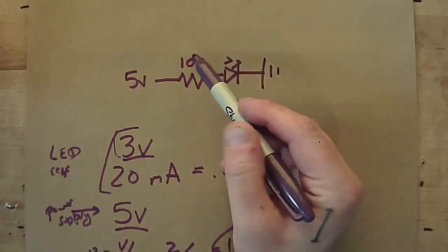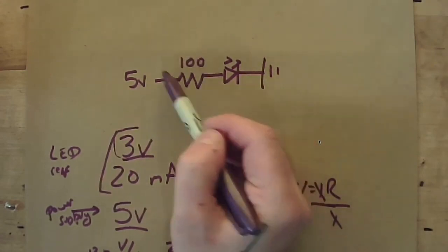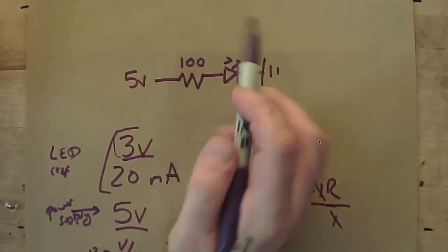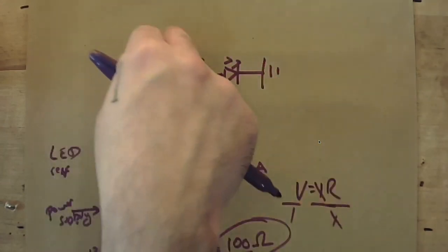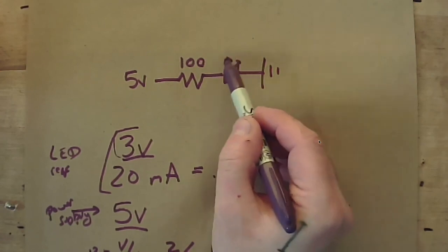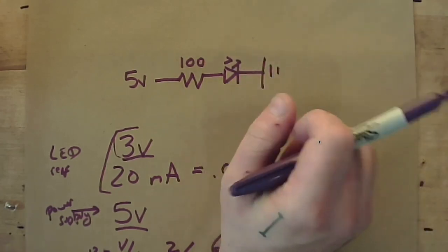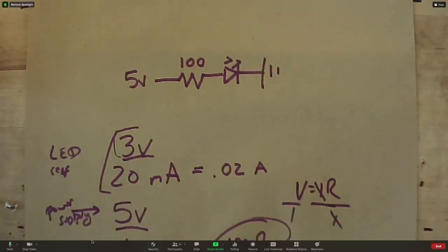So what's going to happen, this resistor is going to manage the flow of electricity. We're going to use this resistor to set that hose size that's going to let those electrons through, so that now when this component turns on and it gets its very low resistance, it's not going to burst. Well, it doesn't burst into flames. It just kind of stops working. But this is an implementation of Ohm's law that if you ever use an LED, you're going to want to use.